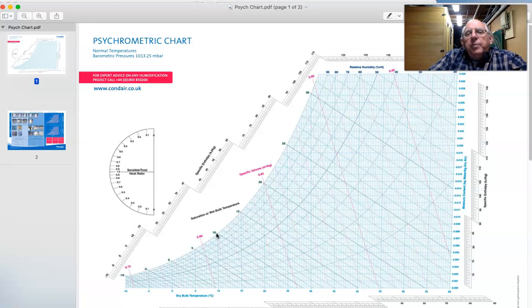And so what we proposed is that we had two processes. One came down to a lower humidity ratio, and then one went over. In each case, we came over and picked up an enthalpy of the moist air mixture on this chart. We saw that the first case went down and we took the difference and had the latent heat. And then we had the sensible heat.